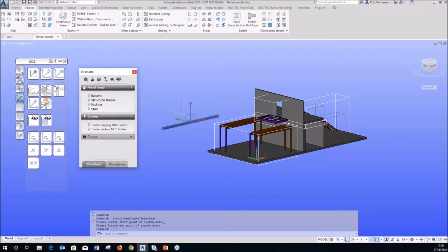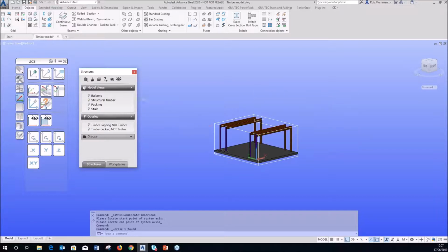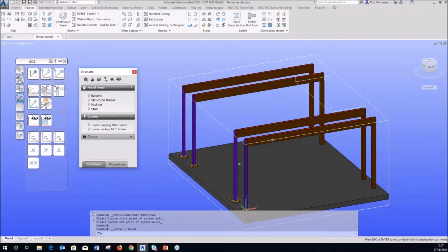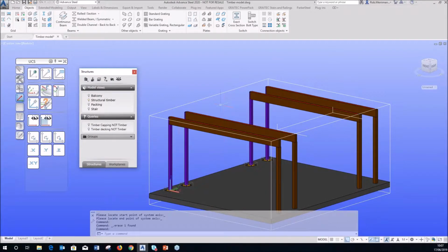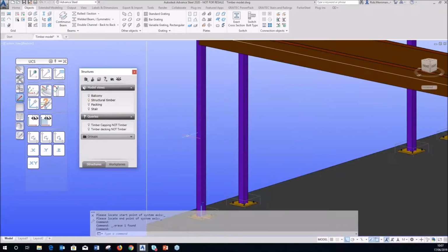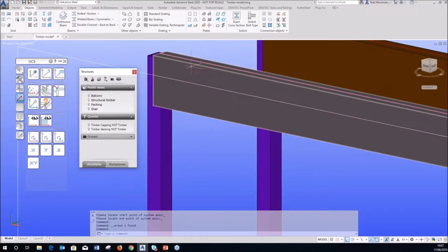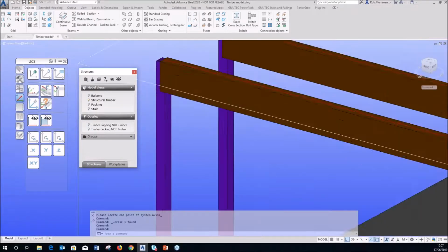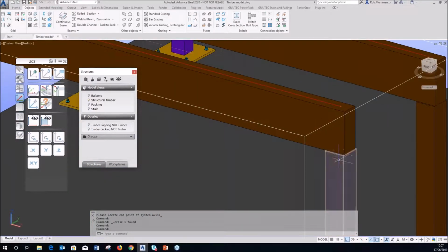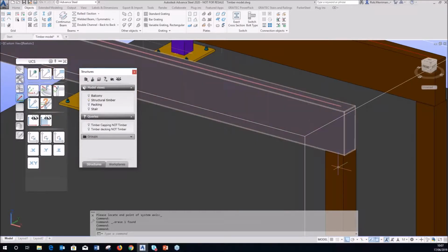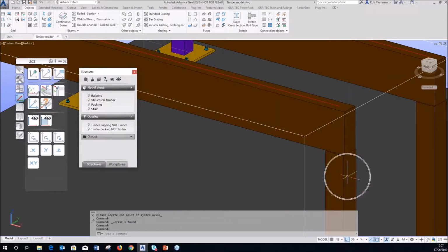What I've had to do in the past, I have worked on projects where we've got structural timber and structural steelwork. So in this little example, we're going to just use this model view just to isolate my structural timber. We've got some hot rolled box section columns, so some steel columns with a glulam beam. So I need to put a fin plate connection in there, and I need to put a plate between. I've got a 140 glulam column in here.